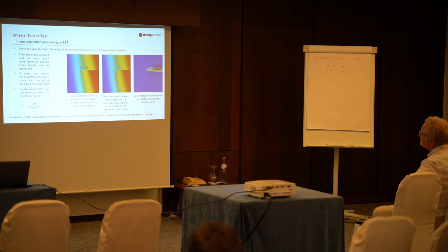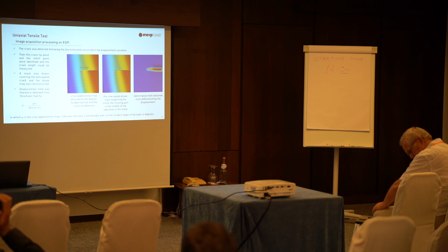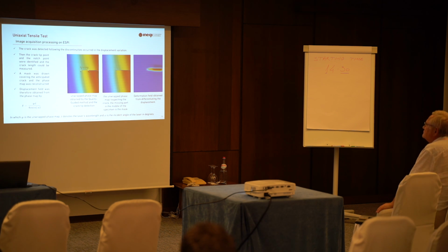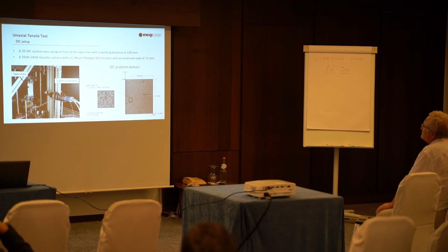Based on fracture mechanics, when we have any crack or defect in the structure, we expect to see discontinuities due to that defect. So we founded our approach on these discontinuities. Through the ESPI outcome, it was possible to detect and identify the crack tip, the notch tip and the crack lengths, and then compare them to what we got from the fatigue test.